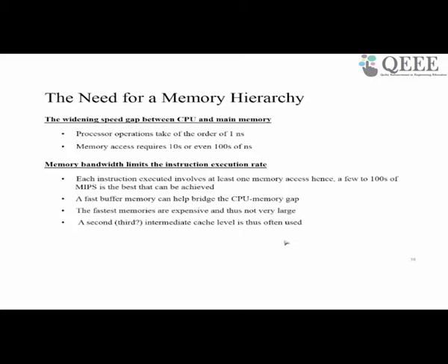This cannot be met by one memory from a given technology alone. If you only have a semiconductor memory, it is costly, and you can't have a large memory for a reasonable cost. If you just use a memory based on an optical storage device, a very large memory can be had, but it will not meet the bandwidth requirement of the processor. So we have to have a hierarchical memory structure wherein we draw memory from different technologies and put it in a hierarchy which meets the requirement.